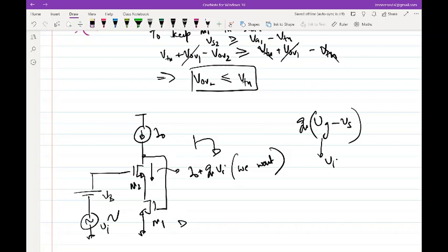Correct. Exactly. So what can we add to this circuit? If I want this, it means that I want VG2 minus VS2 to be 0. So how can I incrementally short M2? Till now we have only learned about one way of realistically shorting any node: add an infinitely large capacitor from that node to ground.